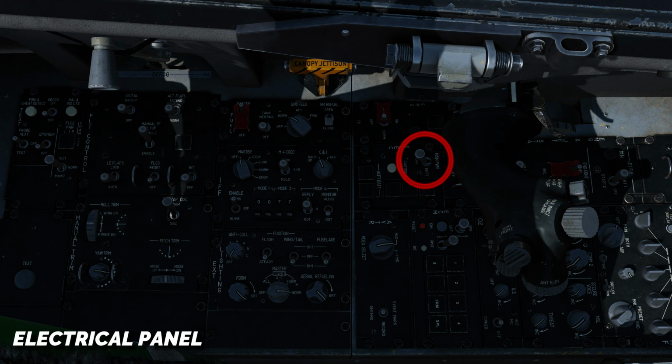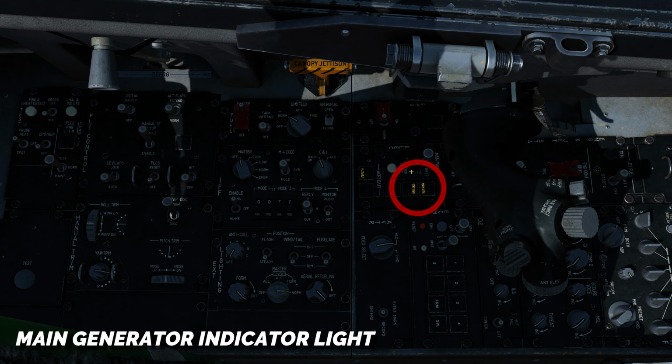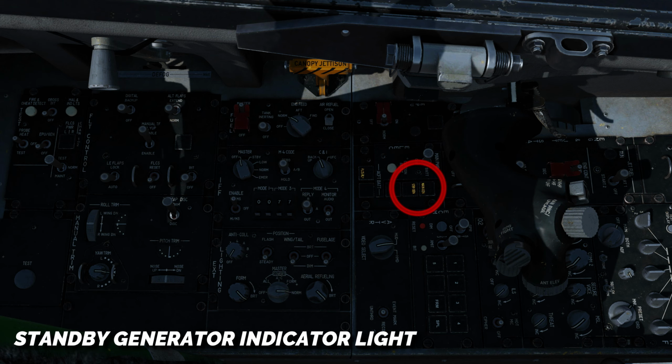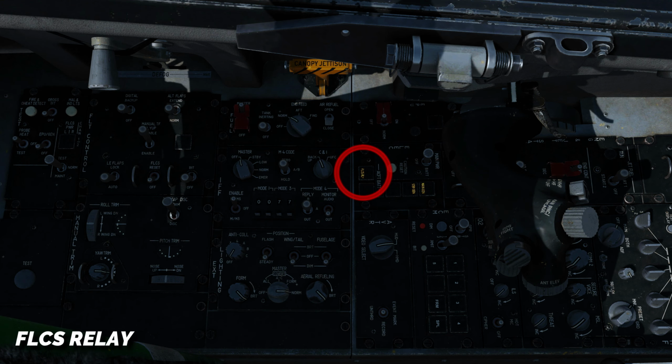To check the aircraft and FLCS batteries before engine start, set main power to battery. External power or main generator are not connected to the electrical system. Standby generator power is not available. One or more FLCC branches are not connected to the aircraft battery, or voltage is below 20 volts minimum.